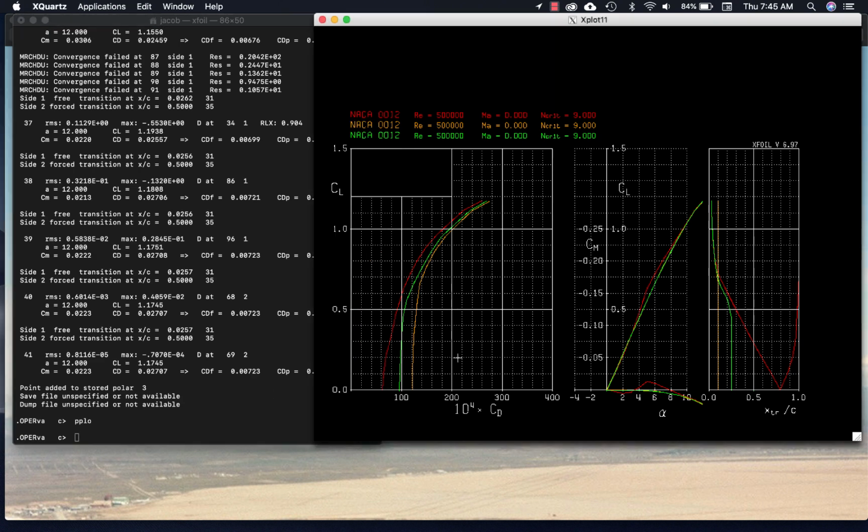So here are my three cases. So I have my natural transition case right here, which, as we saw, looks like, at least for angle of attack of 0, is transitioning around 400,000, give or take. So that's a critical Reynolds number, but that critical Reynolds number is changing, at least on the upper surface, as my angle of attack is increasing.